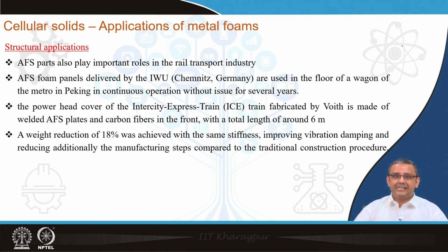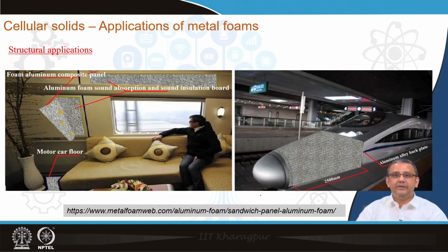Again, the main fundamental aspects which are exploited are the low density and the excellent specific properties like high specific stiffness and high specific strength, because the basic idea is that the performance should not be sacrificed while the density should be reduced, and this way we can reduce the weight of the automobile or the weight of the whole car, and that will in the end lead to higher velocity and also more fuel economy. So, all these things are actually interrelated.